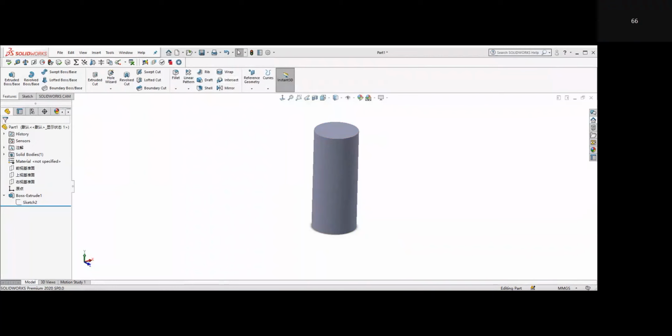I tried to make this, but when I put a dimension and like I put 200, it's not used in millimeter. It's something else, and the picture ratio is very big. Oh, so did you set the right unit right here? The unit set.